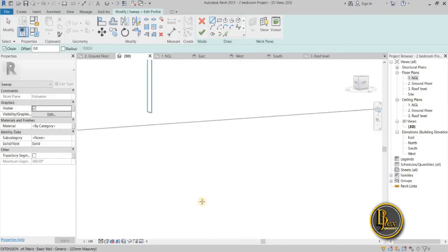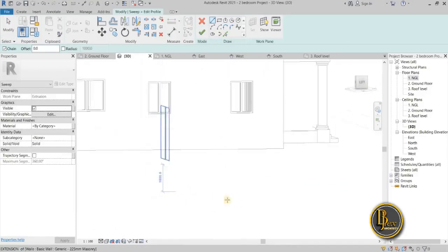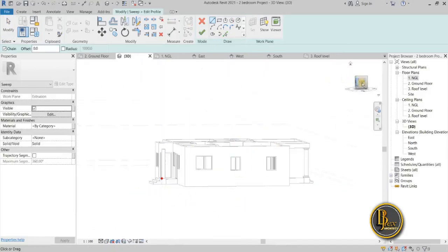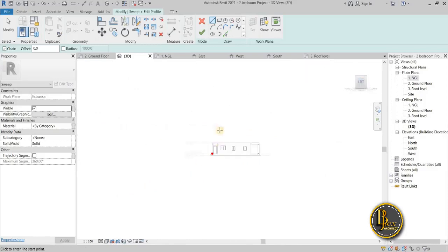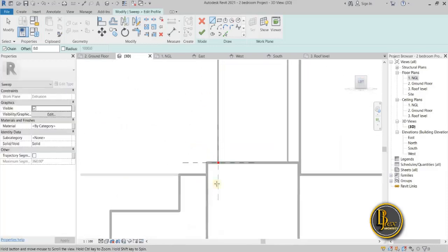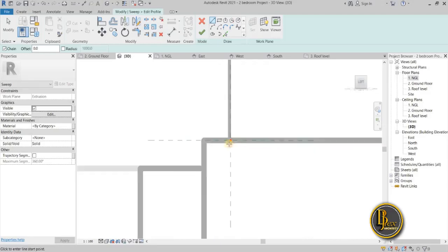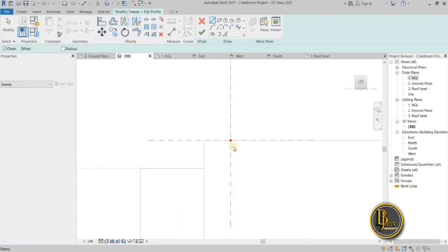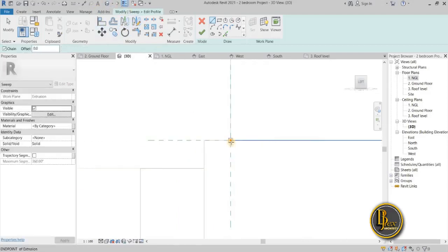Yes, I think we can draw it from this view. Make sure the edges are sharp edges. If you are using left elevation or right elevation, make sure it's a sharp edge. You can actually use your elevation view if you're not using your 3D view, but let me work on 3D. Let's use thin lines, so that if your lines are too fat and you're not seeing what you're doing, you use thin lines.